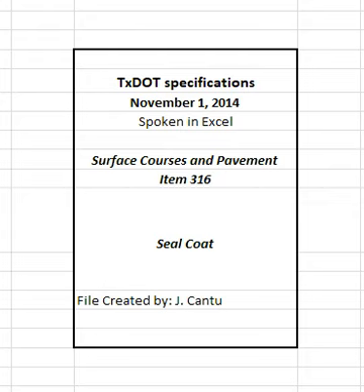4.4.5 Cold weather application. When asphalt application is allowed outside of the above temperature restrictions, the engineer will approve the binder grade and the air and surface temperatures for asphalt material application. Apply seal coat at air and surface temperatures as directed.